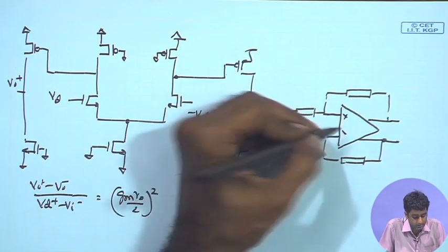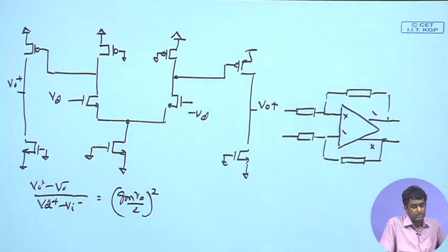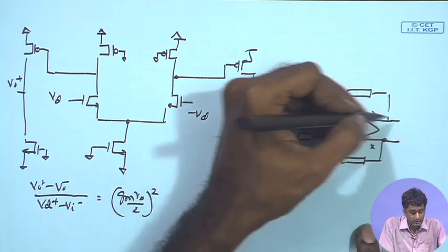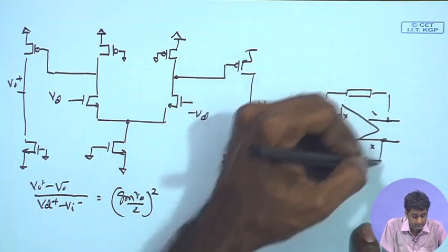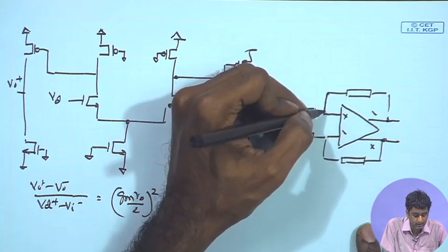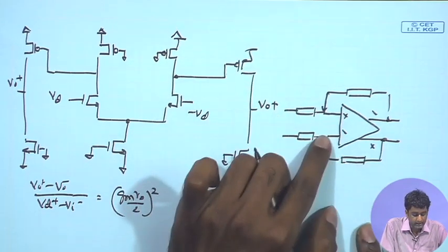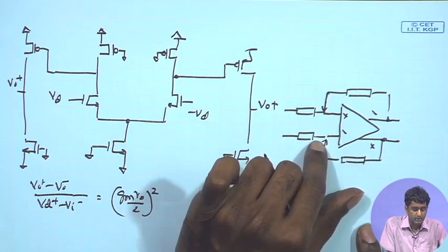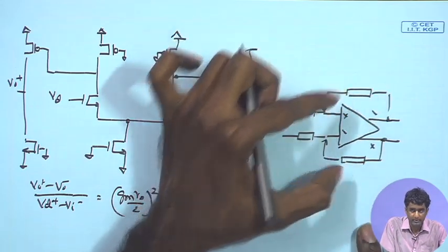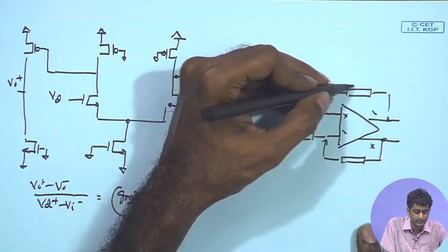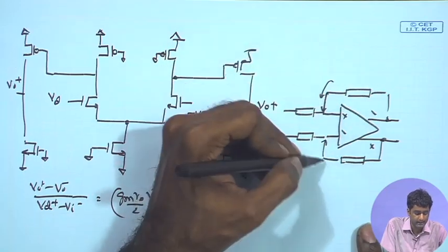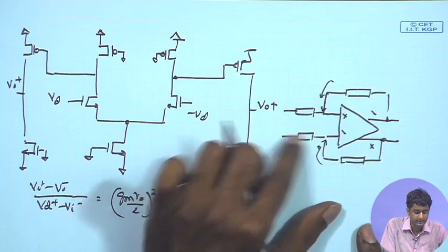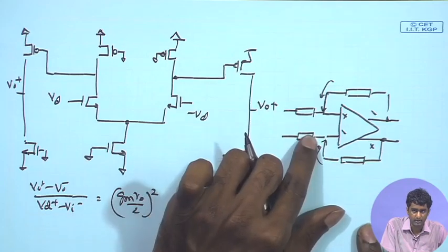If I assume this is plus minus and minus plus. So, we are having the output voltage being sampled by this feedback element and being combined in shunt manner with the input signal. Therefore, at the output we have voltage sampling, but at the input we are seeing that the sampled quantity is being combined in shunt. That means, it is getting mixed in shunt or in parallel with the input component.